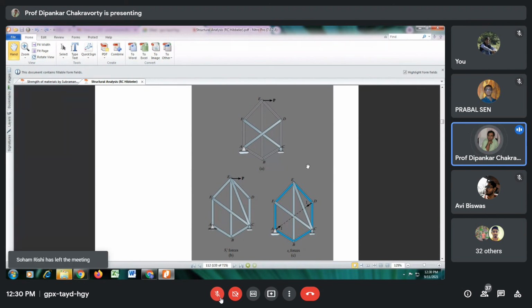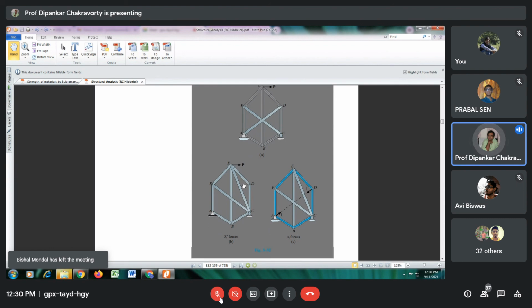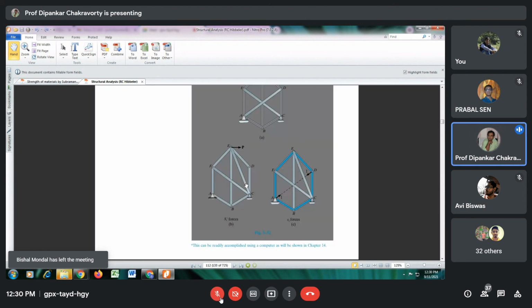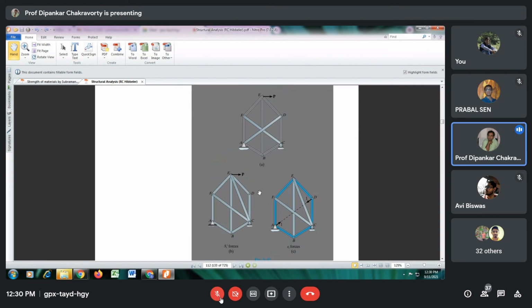Because they have solved it twice under P forces, they have given unity and they will solve it numerically and multiply everything by X. Because if this is 1, then they get the bar forces. So if this is X, multiply all the bar forces by X. That is not a problem. When I was a student, I used to just solve them by assuming this is X. But by withdrawing member AD and by inserting member EC, I am not destroying the basic triangle of any member.